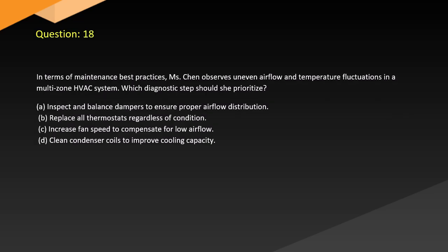Question 18. In terms of maintenance best practices, Chen observes uneven airflow and temperature fluctuations in a multi-zone HVAC system. Which diagnostic steps should she prioritize? A. Inspect and balance dampers to ensure proper airflow distribution.